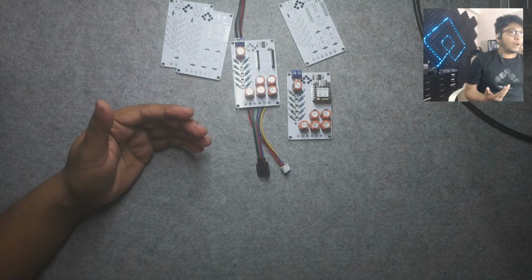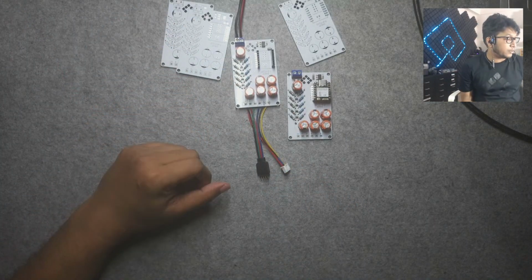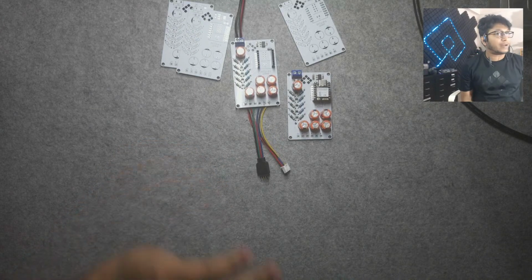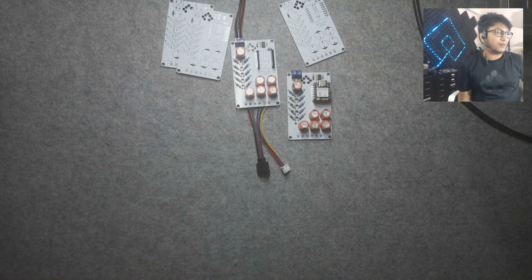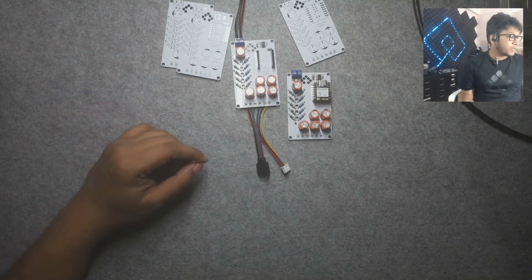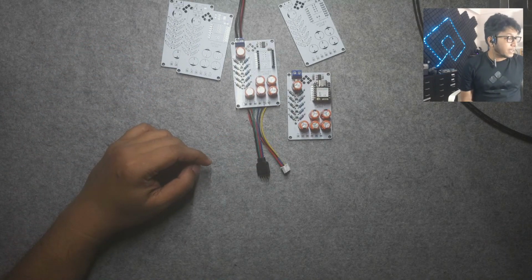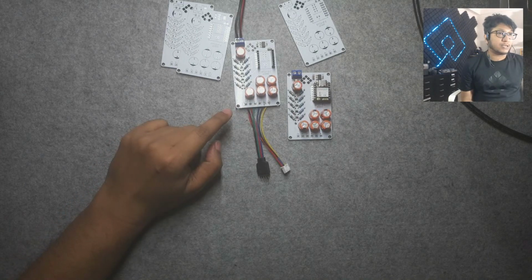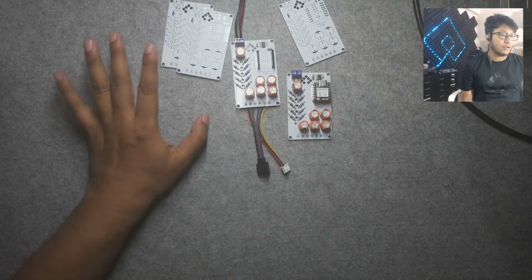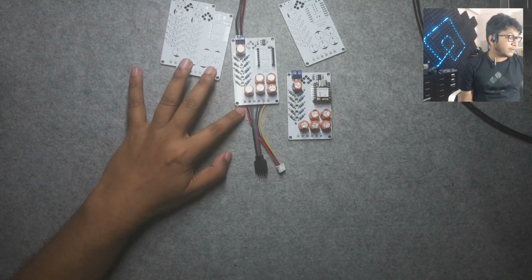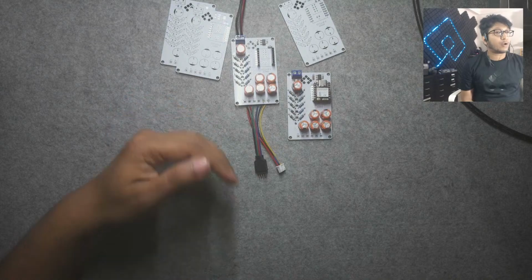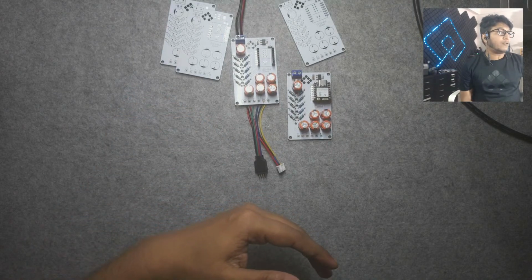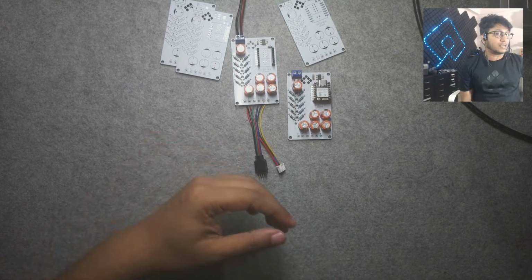I don't have to know exactly which kind of LED module I'm driving. I can drive pretty much anything, as long as they are DC LEDs, you can drive it from here, right? Yes, there is no constant current regulation here, and that's a choice that I made myself. So these are not constant current drivers, but they manage. You can manage even if you're driving an LED without a series resistor.